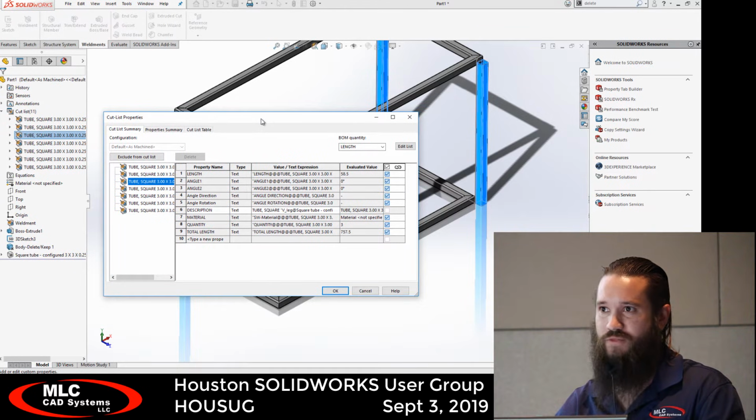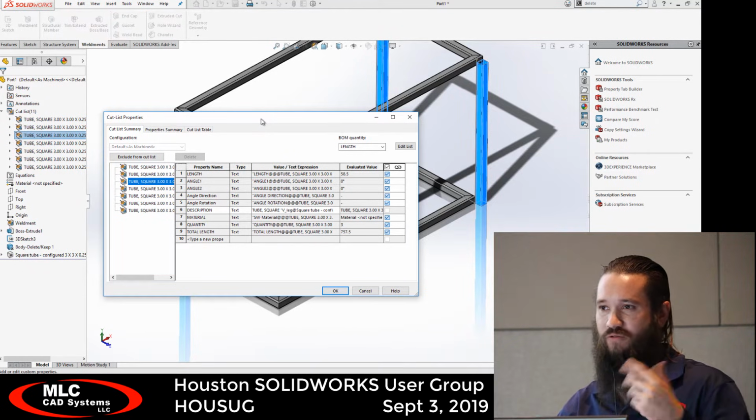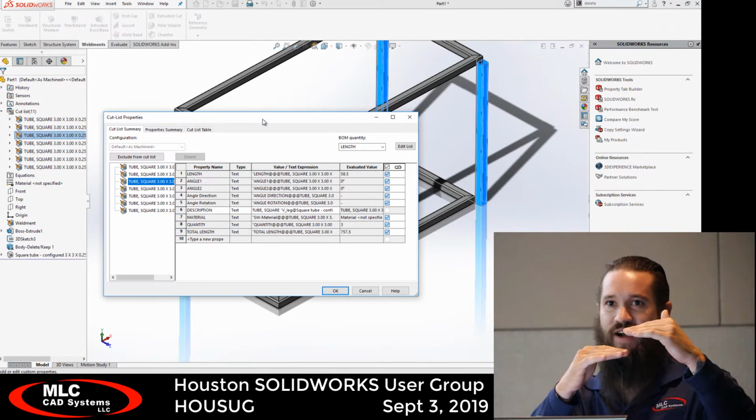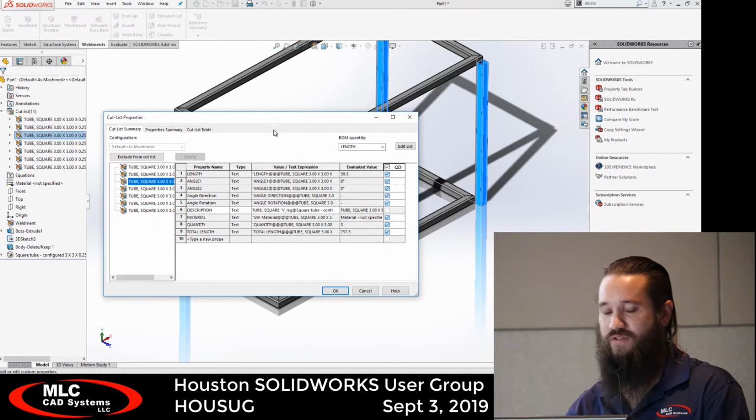And a good rule of thumb too, while you're using weldment members, I try and suggest using patterns and mirroring a lot, just to make sure that if you have weld prep, like for bevel welds, you don't forget to add a chamfer or something on one side and then end up with a separate cut list item because the members aren't identical. So try and use a lot of patterns and features if you can.